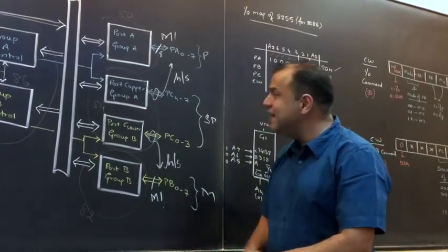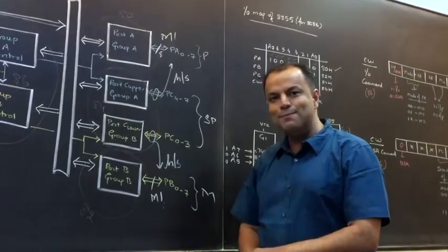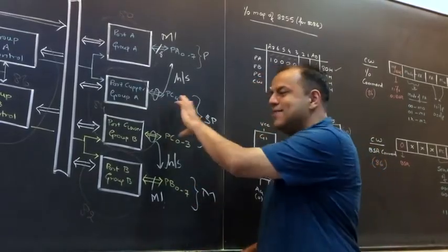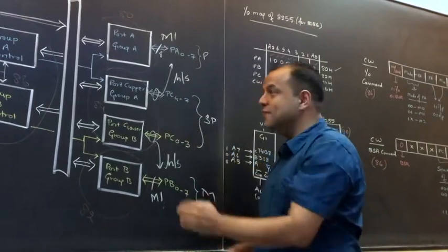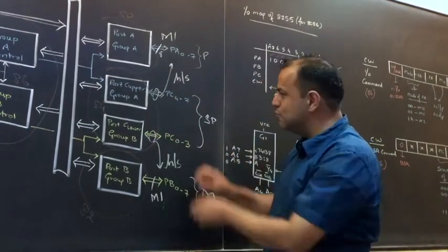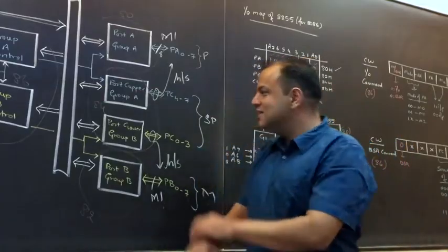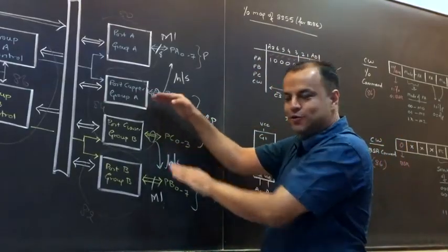Did you understand? If port A and port B are both in mode 0, they don't need any lines for handshaking, then port C is free to transfer data. But if port A and port B go into mode 1, they take away lines of port C to perform handshaking. Are you clear? That's why port C is shown as divided into 2 parts.